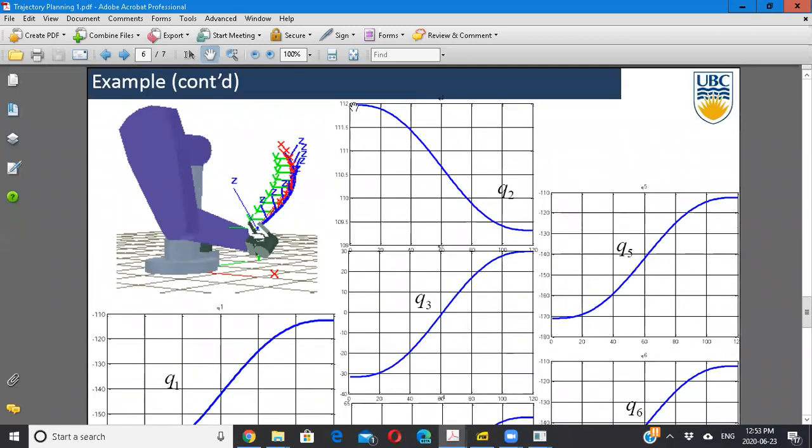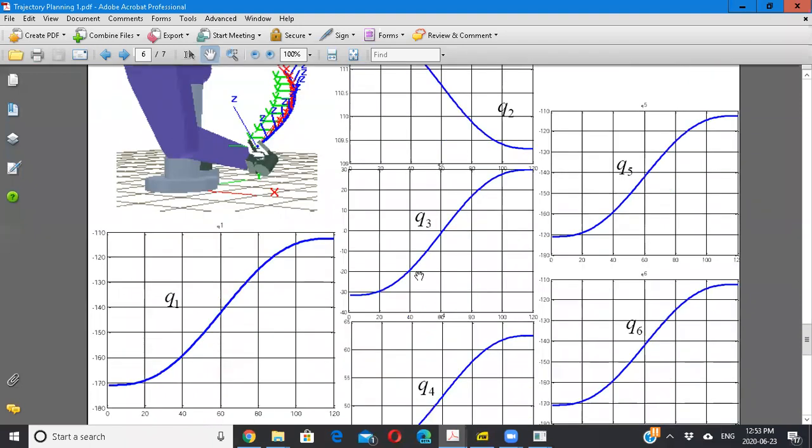Just the qi is changing. Look, qi is 112 degrees, qf is this, and initial velocity, let's say it's 0, final velocity is 0. So just the a's coefficient will be different for this one. For this one, the initial qi and the final qf are different. So again, it will have its own a's coefficients. That's the only difference between the two trajectories, the coefficients of a.